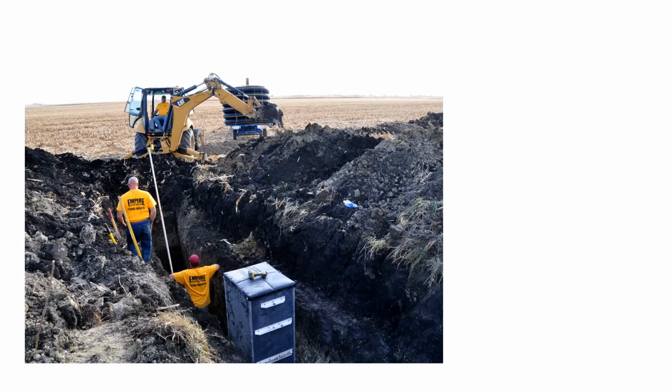Looking at the installation, you set your control structures. It's also a very good idea to have an outlet established before you start digging your pit, just because if it's a wet year and water starts filling into your pit, you want somewhere for that water to be able to go. You don't want that water to get in the way of a good quality installation.